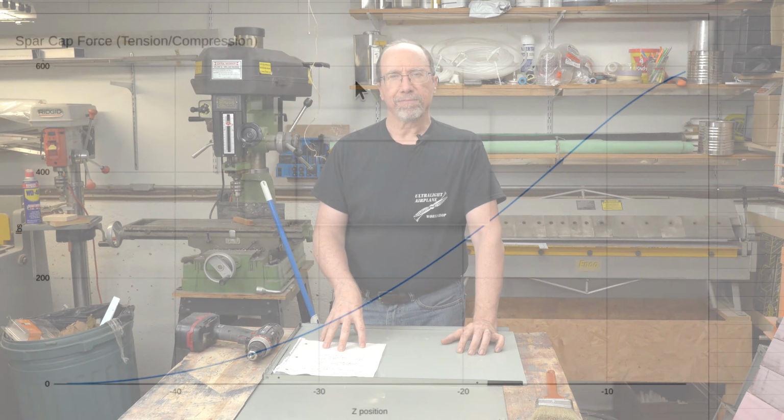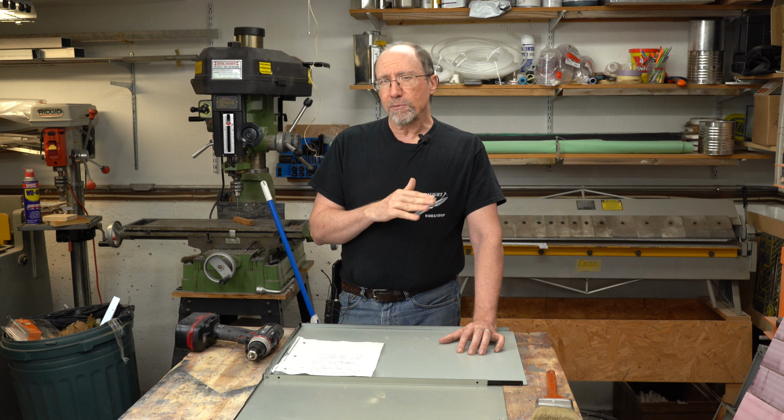I need to provide a few caveats about using the vortex lattice method. I talked about normalizing those lift distributions for a total load of 105 pounds. One of the things I really didn't talk about earlier was that for that left yaw situation, when I looked at what the total lift was that I was getting from the vortex lattice method, it was up around 170 pounds. But you can't really trust that number. We've got an angle of around 16 degrees. That's going to be up really close to what the stall angle of attack is.